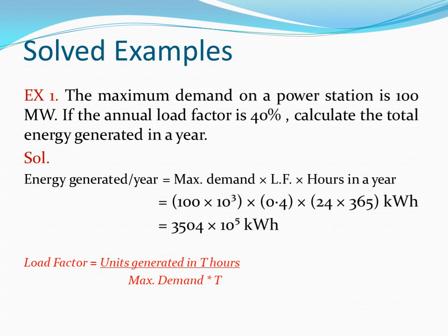Now let's solve some problems. So this is the question given. In the question they have given the maximum demand as 100 megawatt with a load factor of 40%. Then calculate the total energy generated.